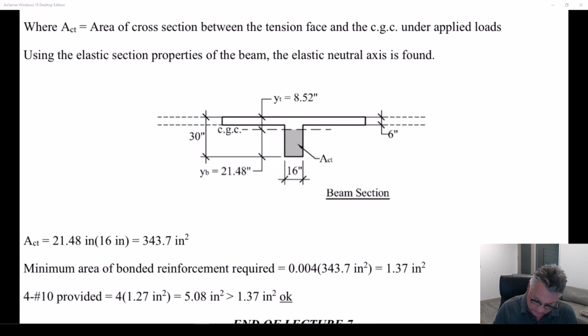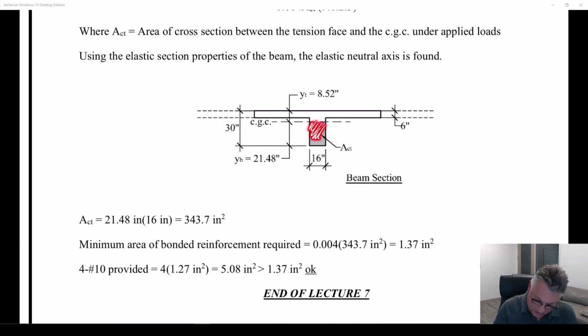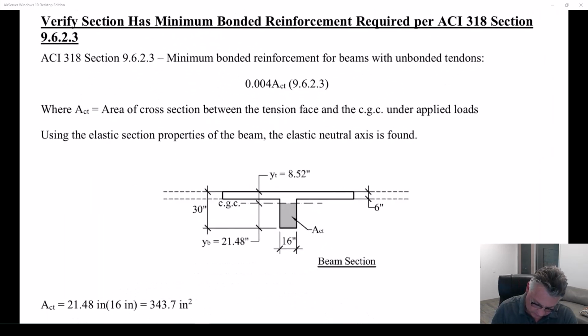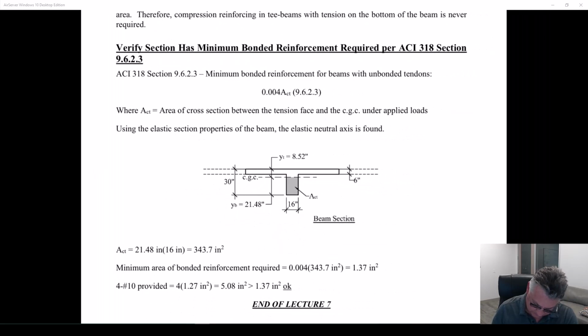Then what we just did was calculate the area of steel on the bottom for positive bending sections, and that will tell us the absolute minimum area of steel that we must have there. We may need more for strength, but we can't provide less than the minimum. So typically we'd start with the minimum and see how well that works. That's what I'm actually going to ask you to do in the project. So in your project, you'll come up with a minimum area of steel on the top of the T-beam that I give you, and a minimum area of steel on the bottom based upon this equation. And that's where we will start. And then you're going to add to it if you need to add to it.